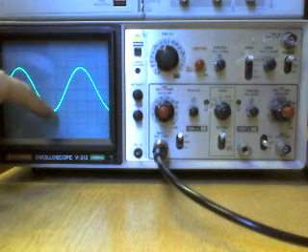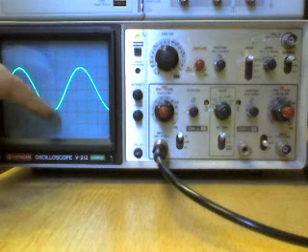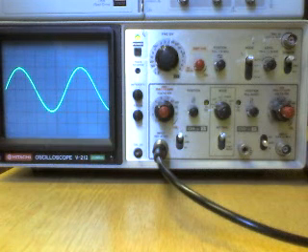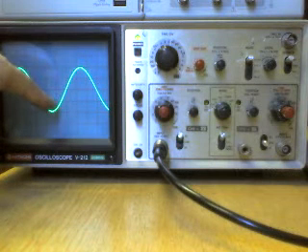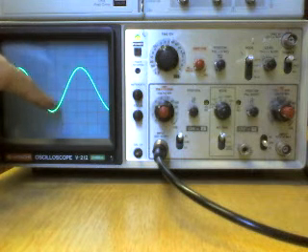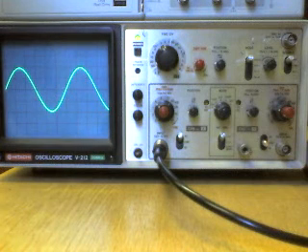Now each of these divisions is broken up into points of a division as well on these oscilloscope screens. So if your signal just so happened to end up halfway in between a division, you can say this is 1 point, and each division is split up into 5, so it'll be one division and a couple of increments more, multiplied by the time base.